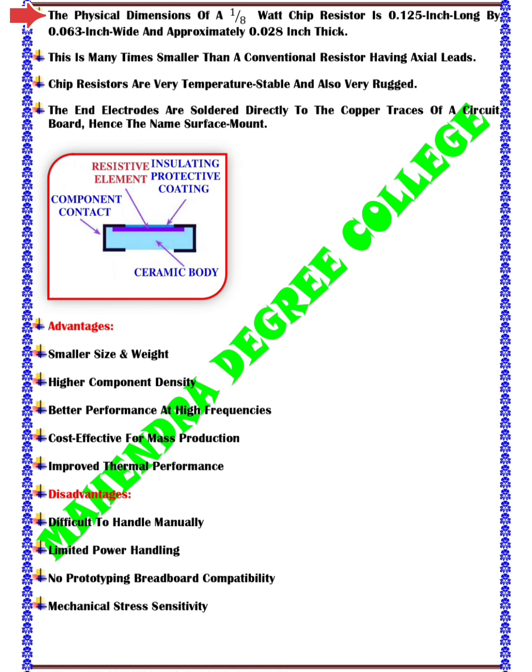Next, a surface mount chip resistor with dimensions approximately length 0.125 inches means 3.2 millimeters. Width 0.063 inches means 1.6 millimeters. Thickness 0.028 inches means 0.7 millimeters. This size corresponds to the 1206 package code in the surface mount device sizing system.